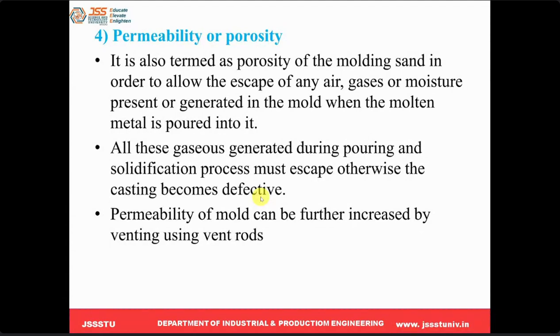Next, permeability. I think you know what it is. This is also very important. Permeability, or porosity of the molding sand, is needed to allow the escape of any gas. Basically, as I said, when the casting process takes place it will produce hot gases, and these should be allowed to escape through that. Otherwise it will create a problem like blowholes.